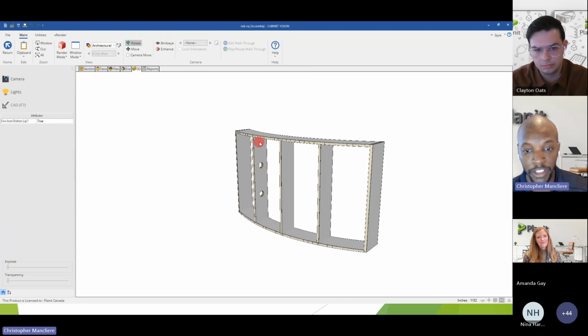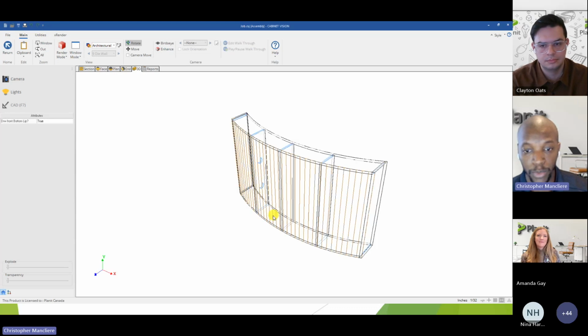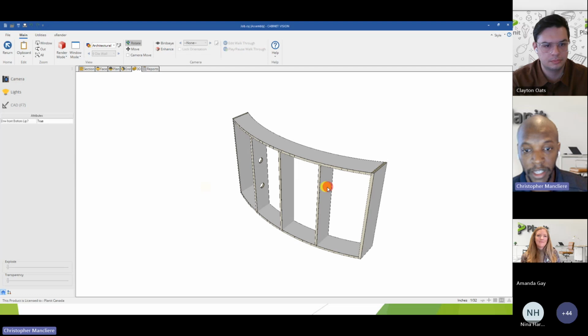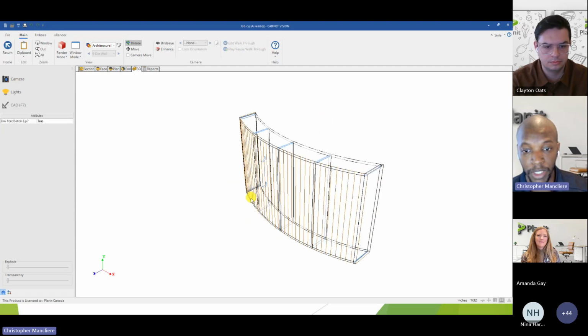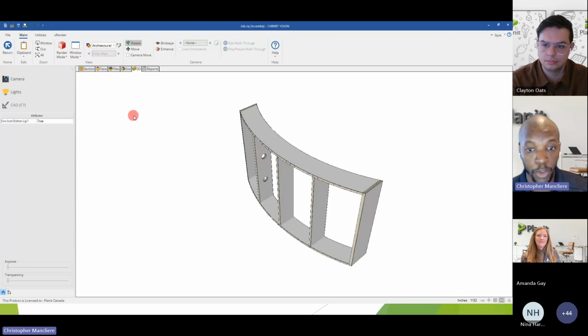And now I can see that I can recall my machining, get my machining back on the part automatically. And this is kind of the same as we did on the backlight example, where the holes will always be spaced out evenly on the part. And of course, you can even add shapes or other operations on the part as well here. So this is really essential if you want to start creating those types of assemblies using shaping. This is the workflow to do it.